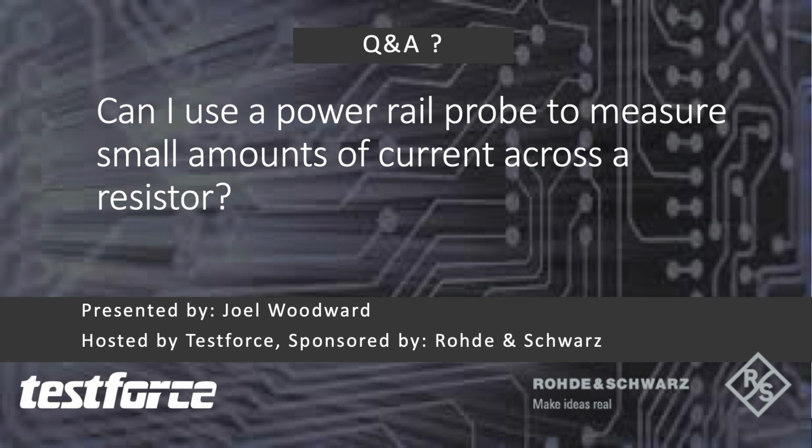The next question is, can I use a power rail probe to measure small amounts of current across a resistor? The answer to that depends. It's actually a really good question. A number of users have a desire to do current profiling or measure very, very small amounts of current. And one idea is to use a power rail probe, which again has very low noise, to measure across a shunt resistor. The answer to the question really depends on your design and the shunt resistor.